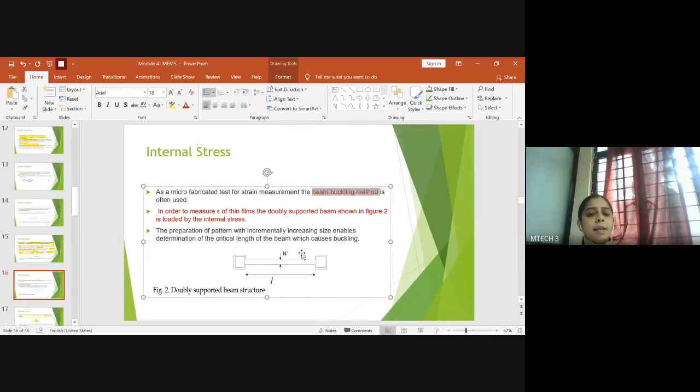It will be like m of x double dot plus k of x is equal to some function where the deflections come into the picture. So if you are able to make a mathematical model, you can see the simulation in MATLAB, or you can use the Workbench of ANSYS and design a simple beam structure, apply the load, show the supports at both the ends, and then check the simulation.